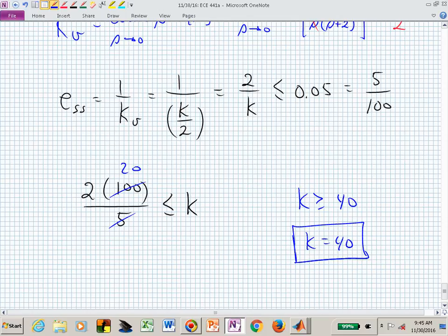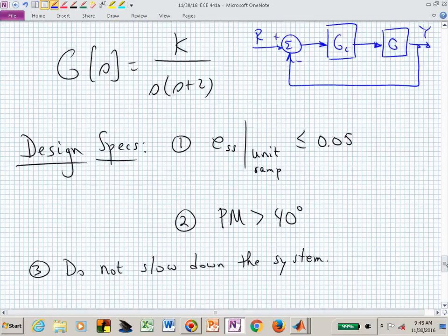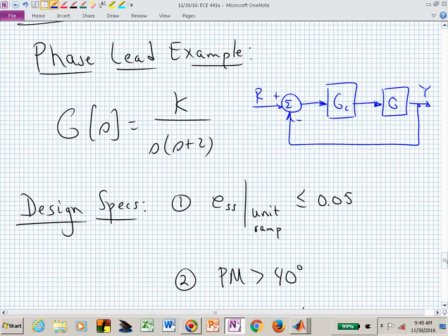Now, you could sketch your Bode plot. Let's say that you get on an exam, or maybe you're in an interview and somebody says, can you sketch the Bode plot of this system and have a steady state error of some amount? You might say, well, let me not worry about the steady state error. Let me just first sketch the Bode plot. And they go, well, how are you going to do that? You just have a K. You act very knowing and you say, I don't really care. I'm just going to set a K of 1, or I'm just going to set a K of 10.